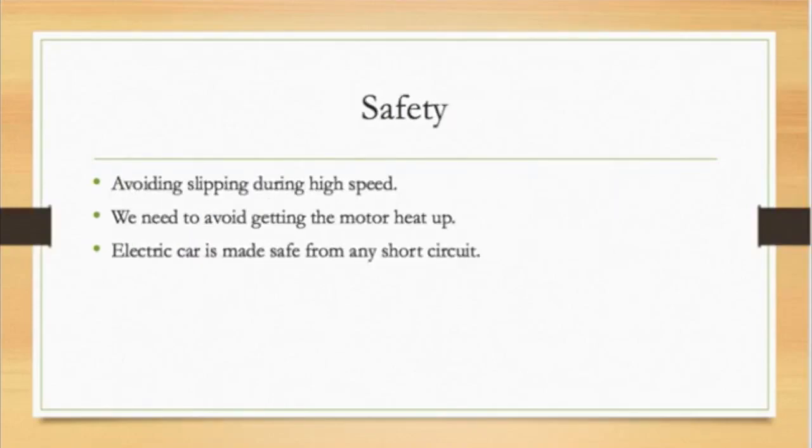The last thing I will talk about is safety. For the safety part, we are concerned about avoiding slipping during high speed. That's why it is preferable to use gear and chain instead of belt. Also, it is important to make sure that the motor does not heat up because that will reduce its performance and might cause problems.